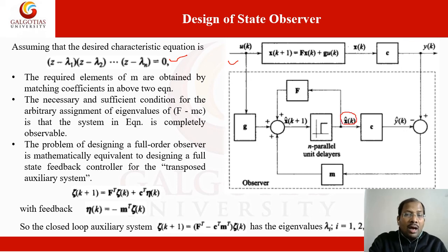When we transpose the observer equations, between the input matrix and the C matrix, it becomes controllable. That means the controllable canonical form can be converted into the observable form, and an observable form system can become the controllable form, which was already discussed in duality.